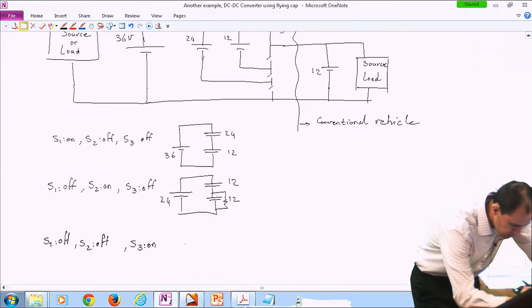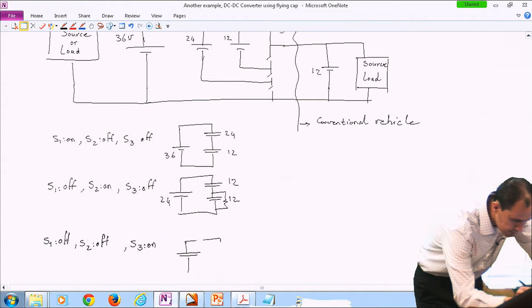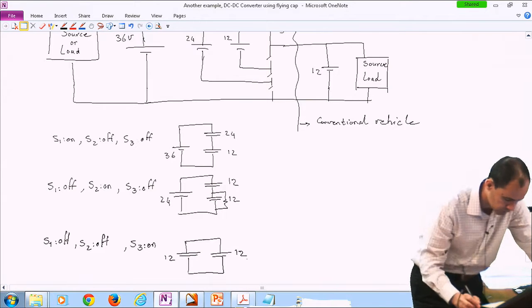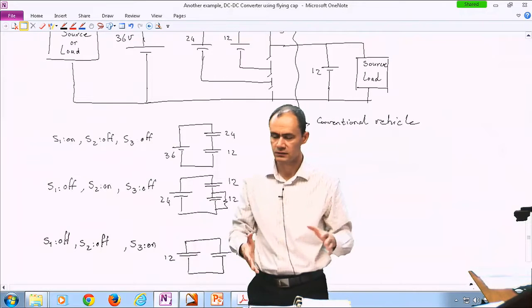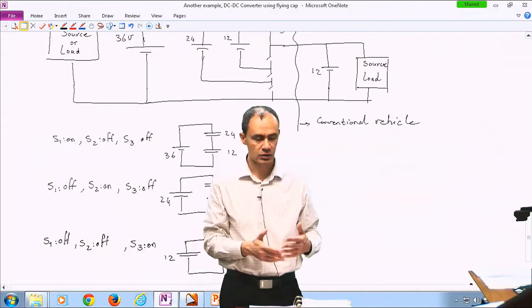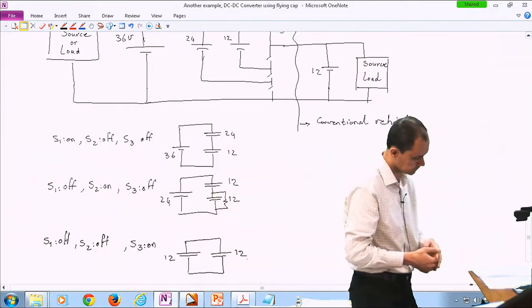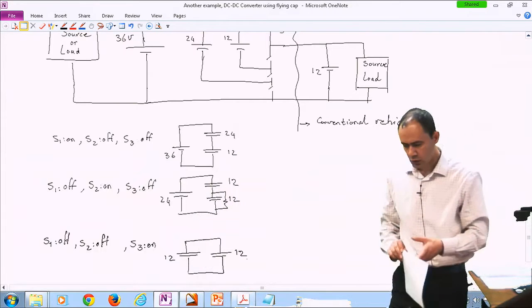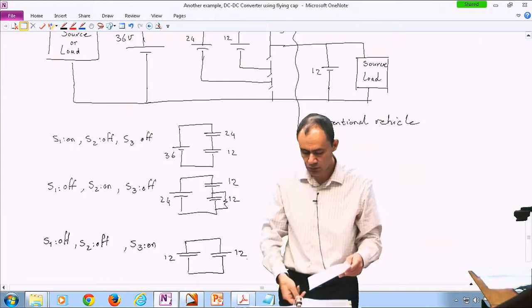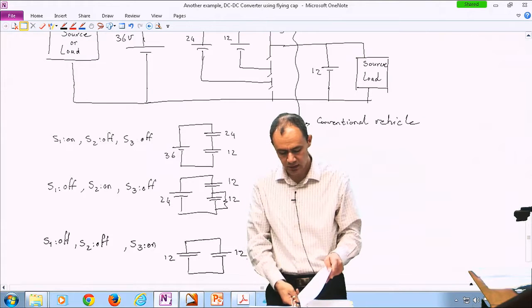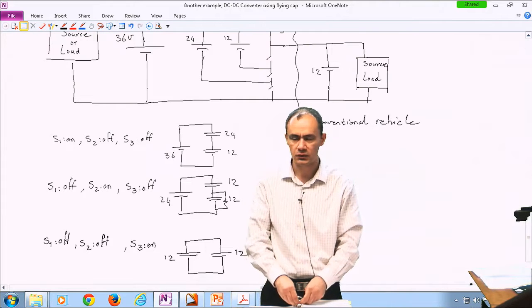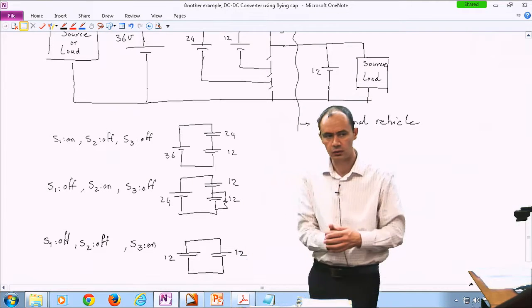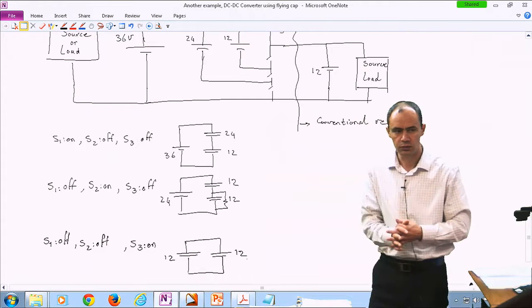So in this case, you have the last capacitor placed with the output side. Okay. So the smallest capacitance in terms of voltage rating is getting discharged and providing power to the load. I've seen there are applications for this for automotive, and remember, reducing an inductor from a vehicle is actually a good thing because it's a portable application. So if you can get rid of a bulky, half a pound or even a pound of inductance, that would be a reasonable thing to go after.